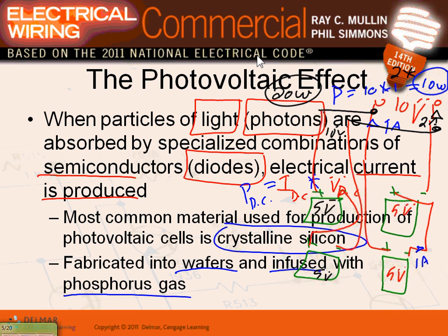If you understand this concept, that's exactly what they do for the solar system, guys. They keep adding panels until they hit the voltage that they want, 600 volt, 400 volt, and then we got the voltage. Now if we need more current, they add another string. They call this one string, another string. So they add another string to get more power. Okay? Any question, guys, about adding panels, series them together to get the voltage, and then parallel the strings together to get more amps? Ultimately, what are you getting? More power.